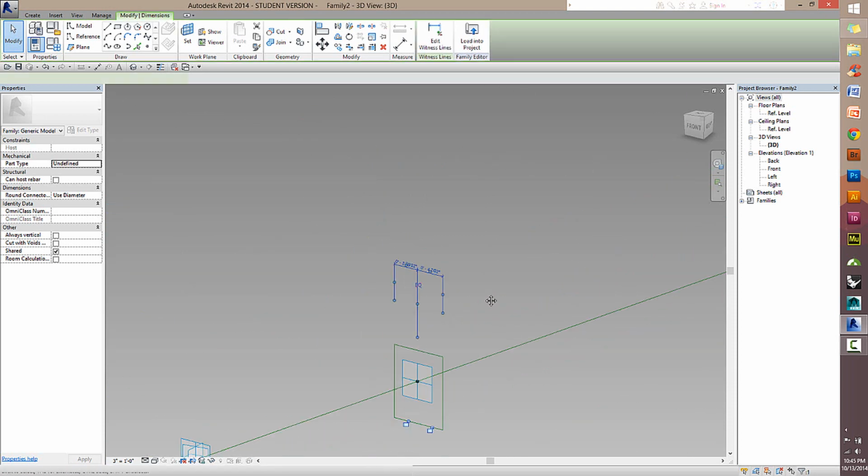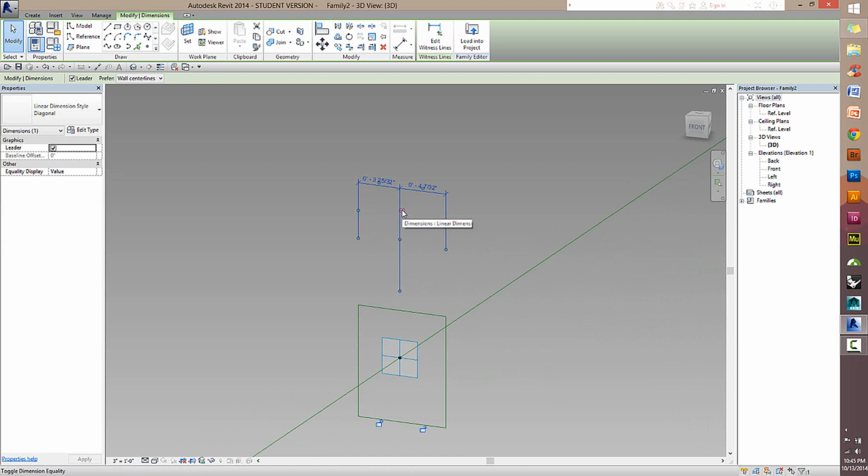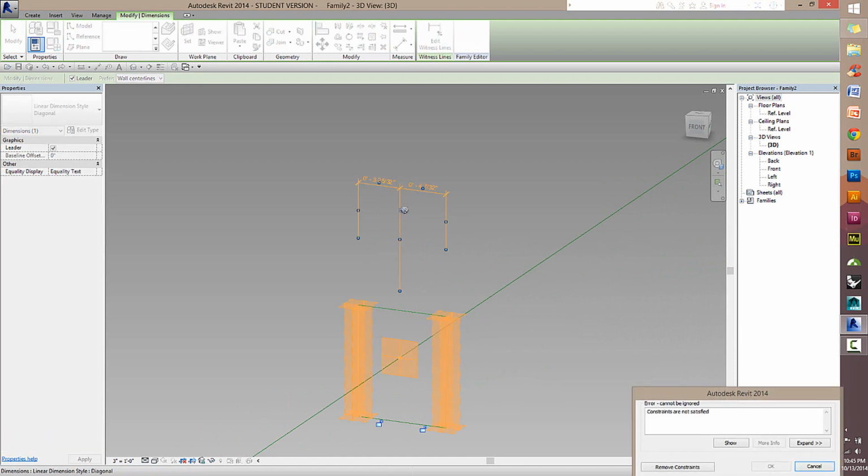And now you'll see that they're a much more reasonable size. So we're going to try setting that equal, but you're going to see this issue. This is something annoying that Revit does occasionally, where if things aren't set equal to each other right away, and you haven't performed a function like this in the file yet, it doesn't understand what you want to move, and it doesn't know how to actually make those things equal. So we're going to go to cancel,